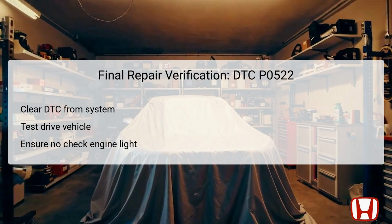After completing the necessary repairs following the diagnostic process, it's essential to perform a final repair verification. Begin by using the HDS or a similar diagnostic tool to clear the DTC from the system memory. Subsequent to clearing the code, a test drive of the vehicle should be conducted.